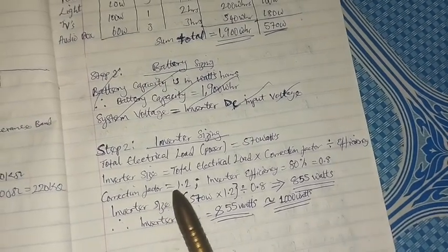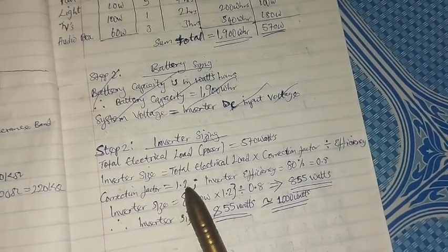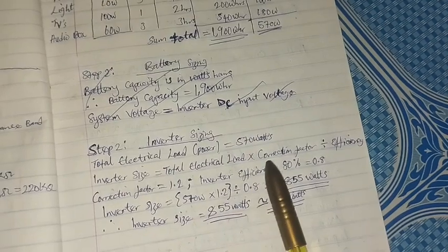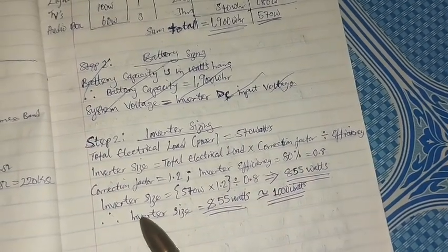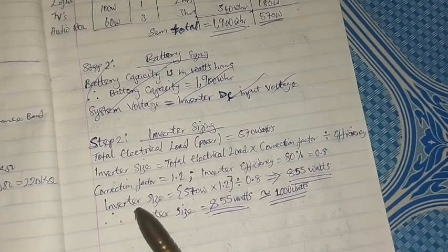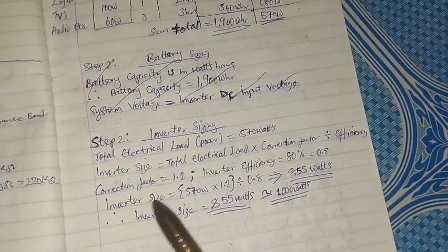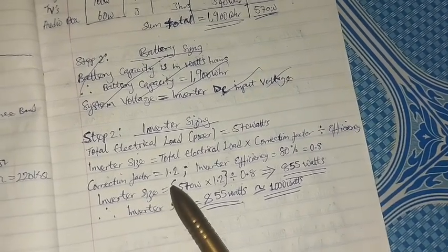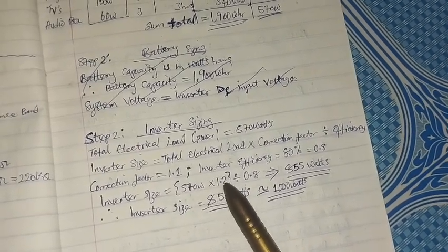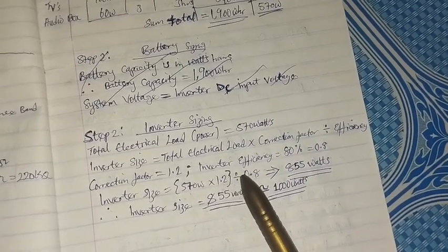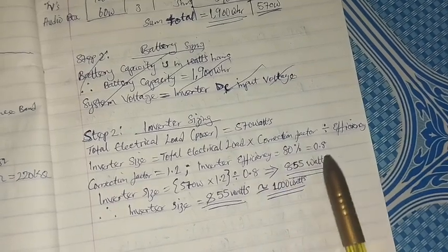Our correction factor is equal to 1.2, and inverter efficiency is equal to 80%, which is equal to 0.8. So our inverter size is going to be equal to, bracket open, 570 watt times 1.2, bracket close, divided by 0.8,